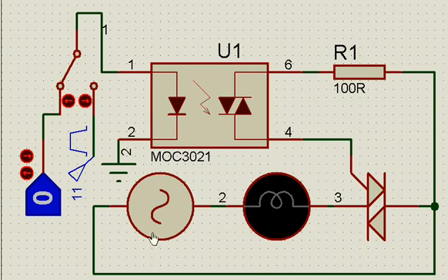We have a supply here, and then we have a lamp here, we have a triac here. All of them are in series. The gate is connected in this fashion from the diac combination of the opto isolator, and we know that the triac can conduct only when the gate is triggered. Triggered means the current has to flow in the gate and M1 circuit. This is M1 and this is M2, or we call it sometimes A2 and A1 of the triac.